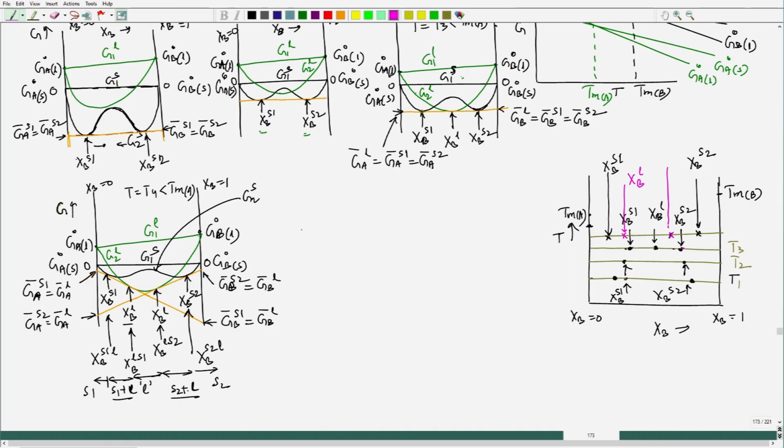So, this is X B of liquid. Okay. So, now I see that at T4 I am getting 4 equilibrium compositions, and we also see from the free energy composition diagram here X B is varying in this way. From the free energy composition diagram, I see what phases will appear as a stable phase at temperature T4, from common tangent rules, as well as of course the free energy hierarchy.